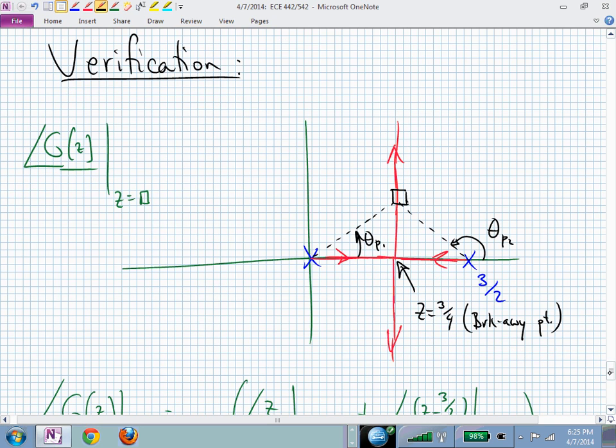Here's your picture. Here's the root locus. You now know this is true for all values of positive gain K. This is where your closed loop poles live. And are there certain values of K that you want to live with or select? Well, you've just found the lower limit. It's 1/2.